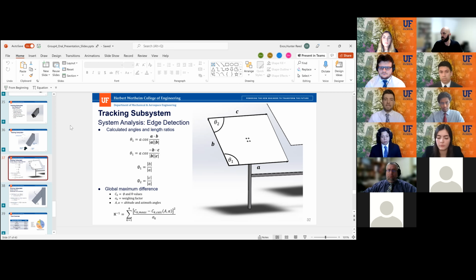And so we decided to do even level heliostat mounting, because we figured it would probably be better to get as much sunlight as we can hitting them, rather than design it to block out the sun by the end of the day. We wanted to avoid that guarantee of, okay, if we stagger them, make them higher, that's going to block the sun once it gets to the other side of the sky.